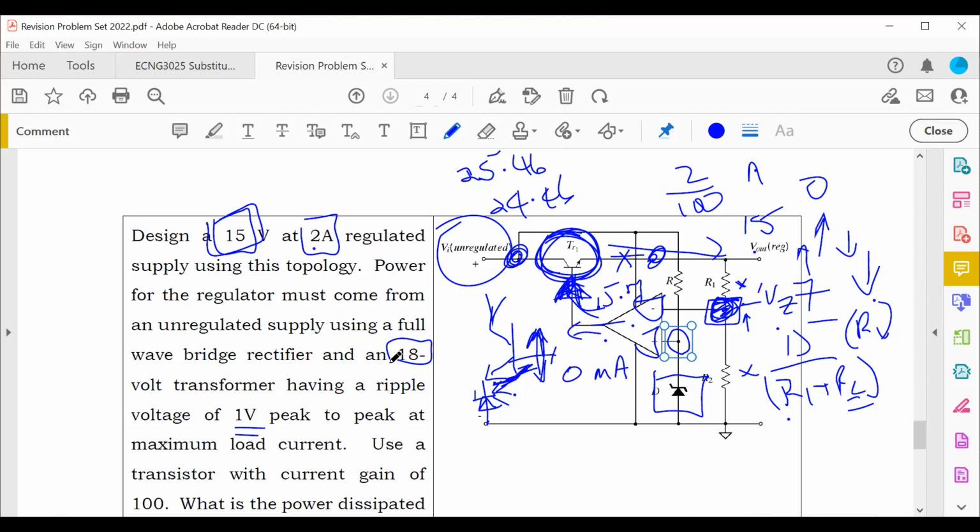That's sounding good on paper until I make a fire hazard. No, well, like we mentioned, this is where the protection circuit comes in. This is why you need fuses and you need overcurrent protection. So you'll put the current limiting on this. You will put in the sense resistor and the current limiter, so if the current goes over 2 amps, it just shuts itself down.